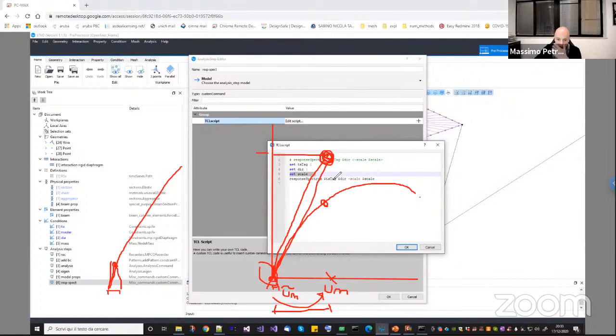So this is still a work in progress. We are working on it. Just to answer the two participants who asked what happens if I do an eigenvalue analysis in a nonlinear environment: do it with care, because it can be inconsistent. So we are working on it. You can do it, but do it carefully, because actually the eigenvalue analysis is not something that should be done in a nonlinear environment. Same thing as a response spectrum. So we need to study this one.